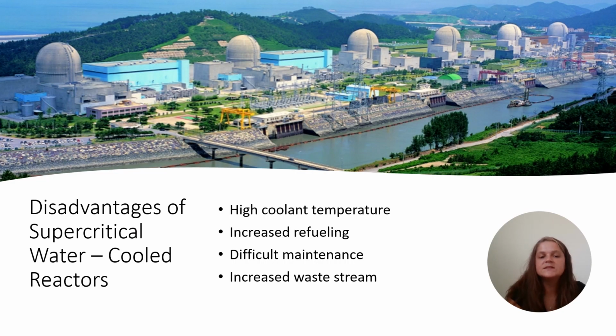And lastly, the disadvantages of supercritical water-cooled reactors. One of the disadvantages is their high coolant temperature. This leads to high cladding temperature, which requires the use of stainless steel and nickel-based alloys as fuel cladding materials. In addition, refueling frequency is increased compared to today's fleet of nuclear reactors.